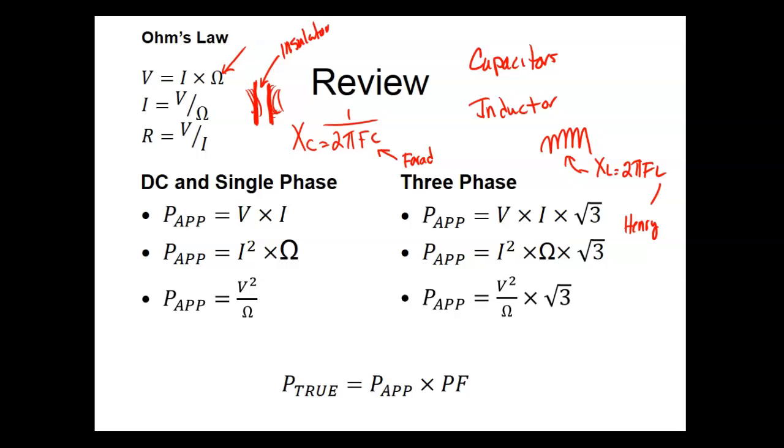If I put DC on an inductor, we've got problems because now all we're dealing with is the resistance of the wire. So this is why an AC relay won't have near the number of turns of wire as a DC relay. Because an AC relay can depend on X of L to get its opposition. A DC relay depends on the R of the conductor, right?